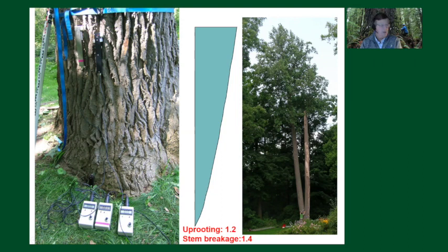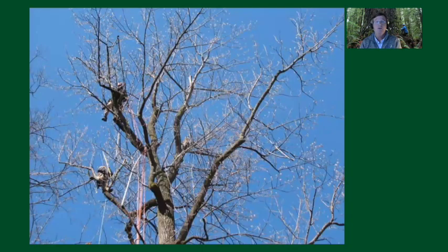One thing we are able to do with the analysis is digitally prune the canopy. And when you reduce the amount of canopy, especially small amounts at the very top, you can certainly increase the safety factor. So we ran that assessment. Then we actually started doing a crown reduction. This here is me up in the canopy of the tree doing that crown reduction, something I very much enjoyed.